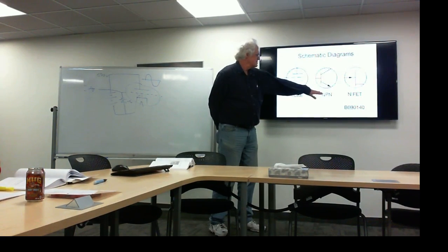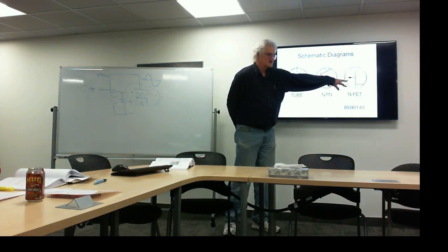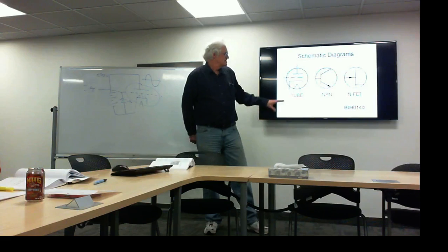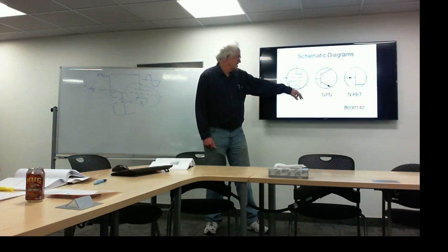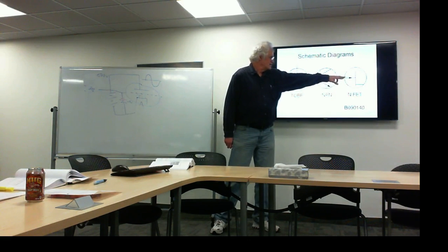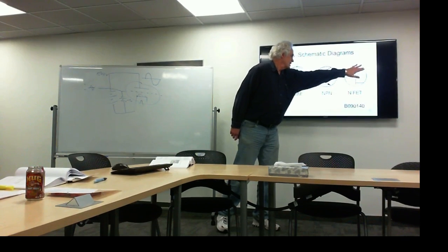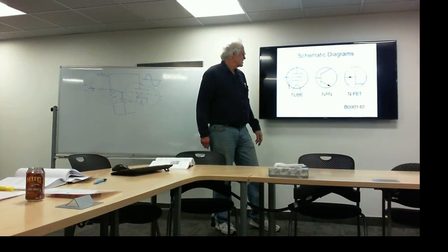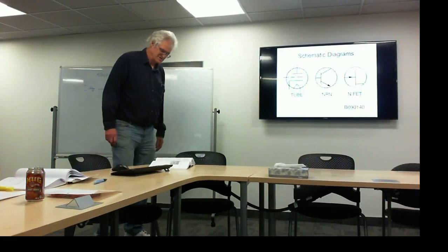Likewise, on a bipolar transistor, you have the emitter, base, and collector. On the field effect transistor, you have the source, drain, and gate. So this shows the equivalents. In a tube, the grid is effectively the same as the base on a transistor or the gate on the field effect transistor. And the drain is basically equivalent to the collector, or the anode or plate on our vacuum tube. Just to put it in perspective, comparing the devices.